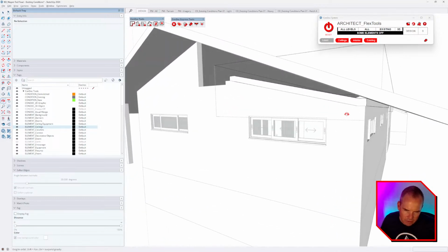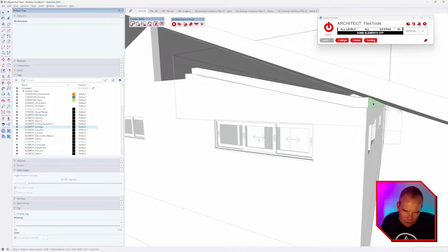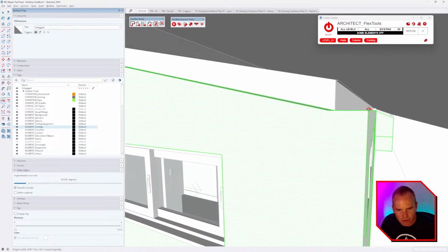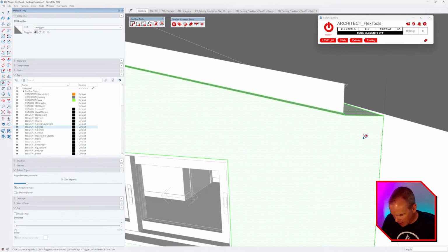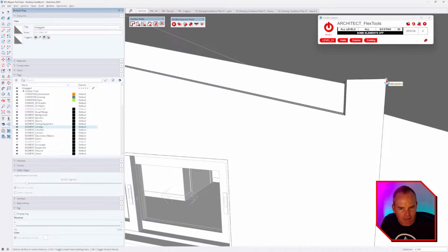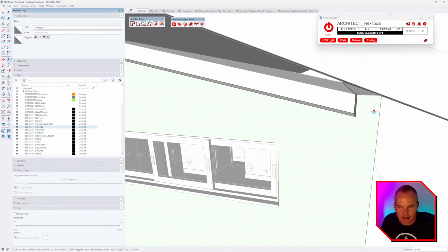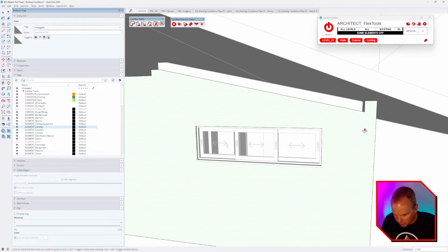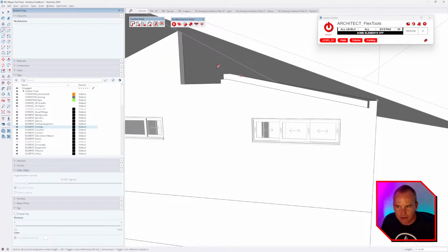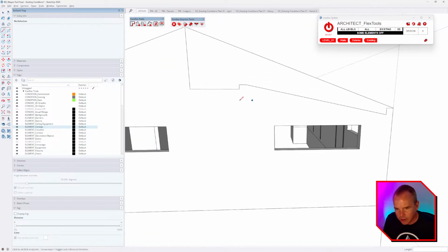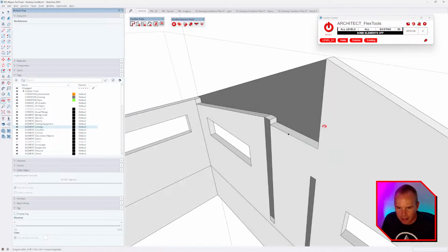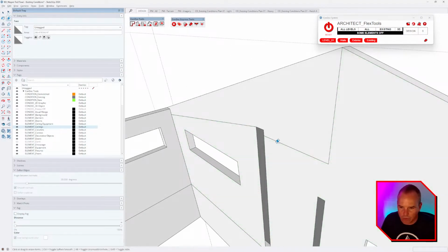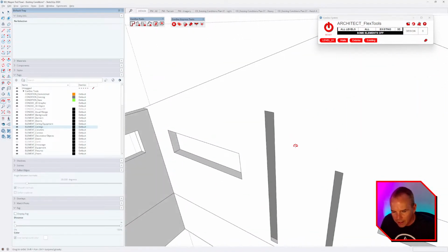I guess I'll push the ceiling in and get our walls to kind of come up like this. So again, I'm going to use my tape measure tool to plot that point and then pull this up. And when I have that grid line there, I can snap to that intersection point like that. All right, and then I suppose same deal. I can draw a line up to here, plot that point. Control H is my keyboard shortcut for hide rest of model, and then I can pull this through like that, and then we'll use our eraser tool and clean this up.